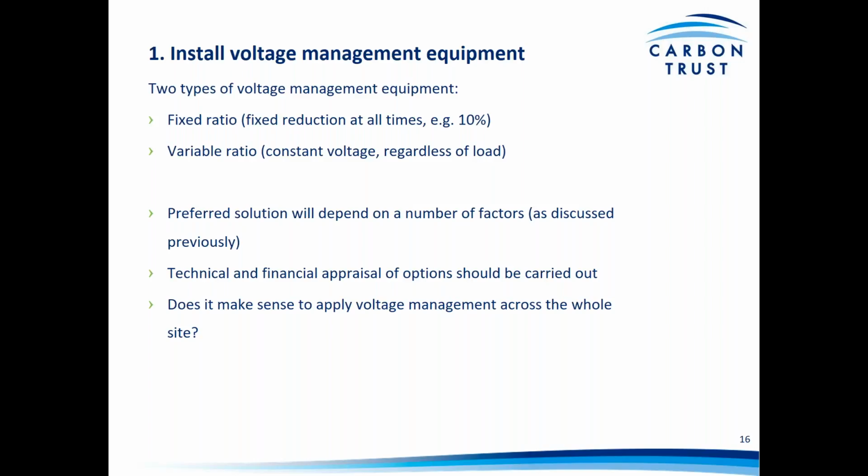A technical and financial appraisal of all the options should always be carried out before making any investment in voltage management. And the final question that we would suggest asking here would be, does it make sense to apply voltage management across the whole site? So there are products currently available on the market, for example, where you can just manage the voltage for specific loads.